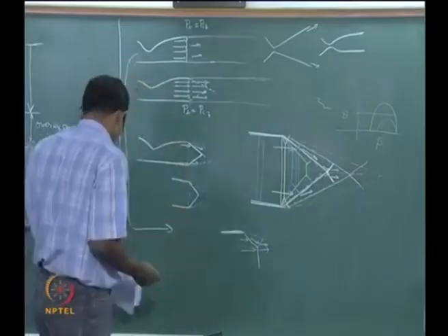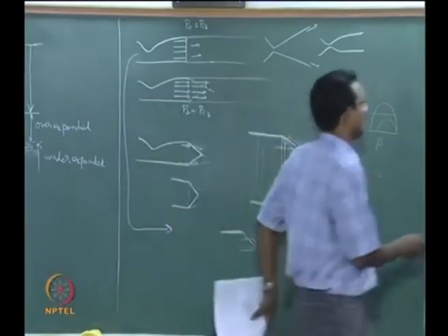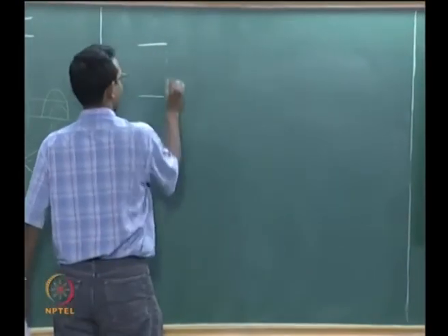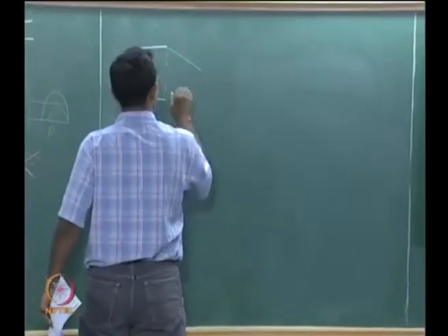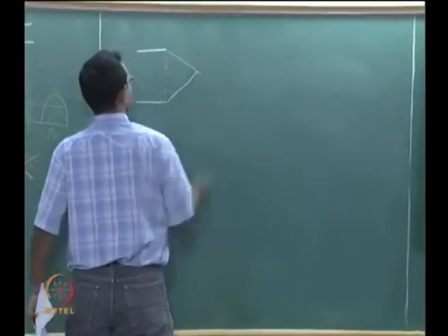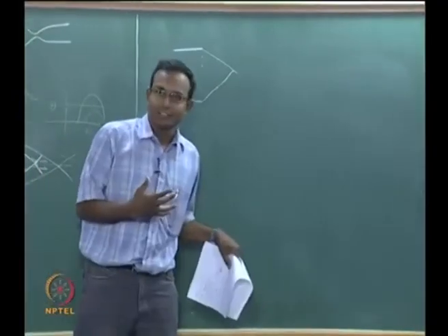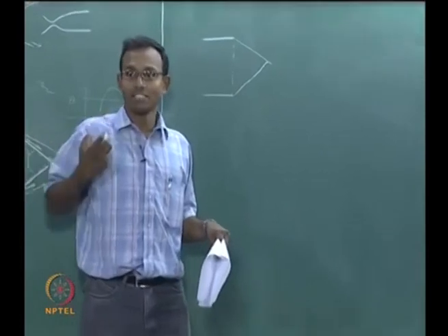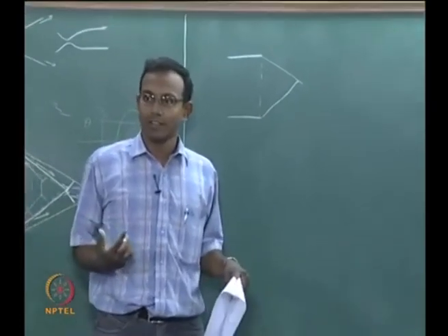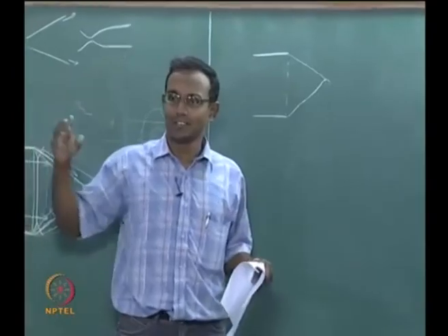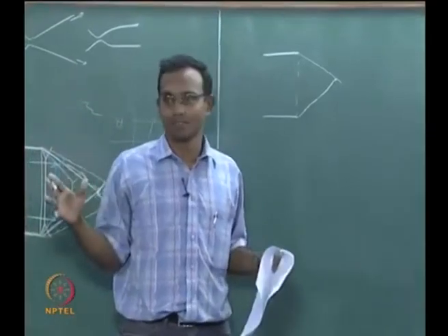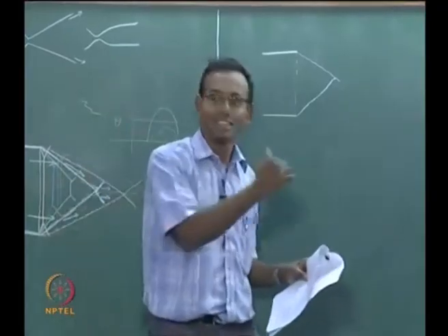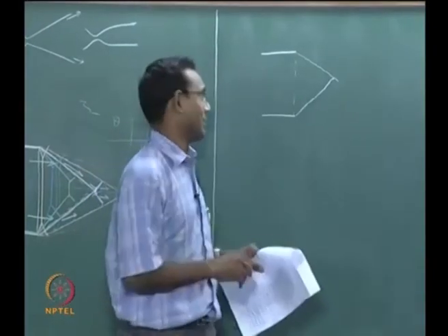So when I look at that, the way I want to look at it is, I will take a simpler case where this is my exit plane and there is an oblique shock, there is another oblique shock, and I want to think about it as each of these shocks are some wave which is carrying a message, right. This is how we did it in 1D moving shock problems. We said if I suddenly close a door at the end of the pipe, the shock travels telling the pipe closed, that kind of thing.